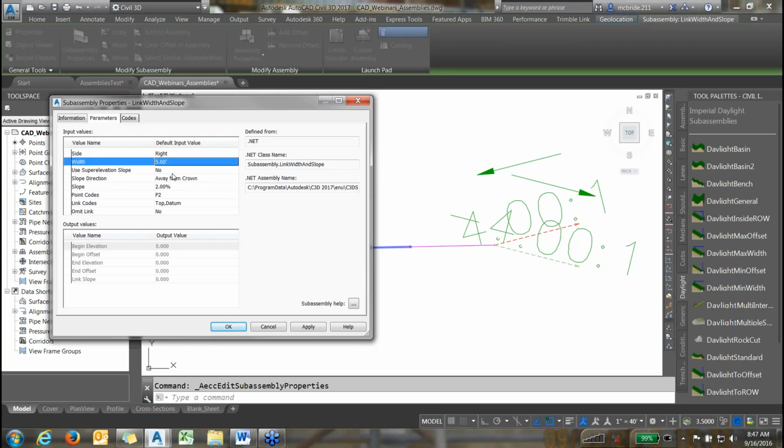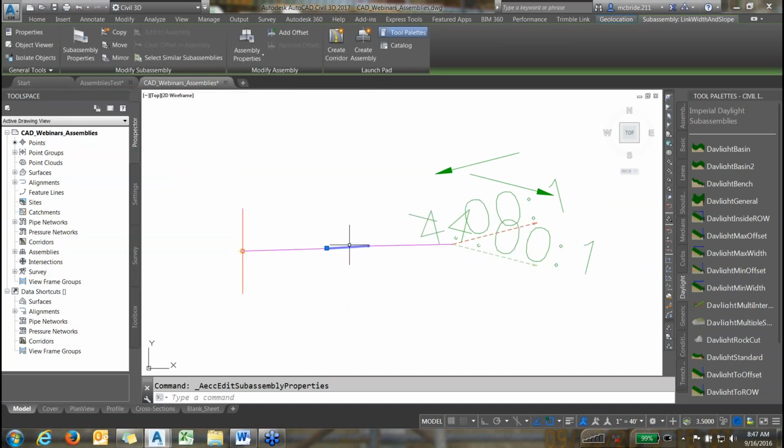And my slope is 2 times that of the first one, which was 3%. So 2 times 3 is 6%. Hit enter and hit OK. Okay, so you can see that one changed a lot because we changed the length of it. It's half the length of the first one, and it's a little bit steeper than the first one as well. Okay, so I'll hit escape.